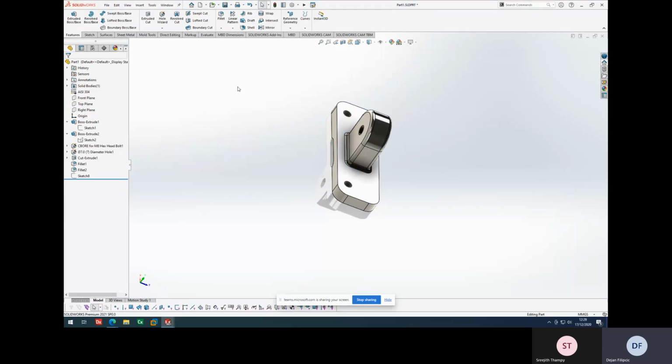Before, this extrusion was on the edge of the plate, which meant when you did the radius, it detected the edge because it was attaching to the edge. But now because it went to the center, the definition of the radius changed, and it didn't do a radius on the outer side of the plate because it didn't have a connection to that, and we didn't pick that yet, right?